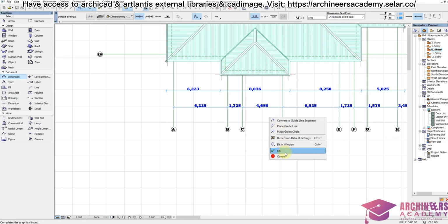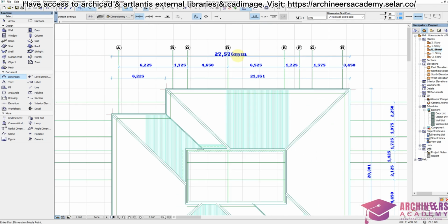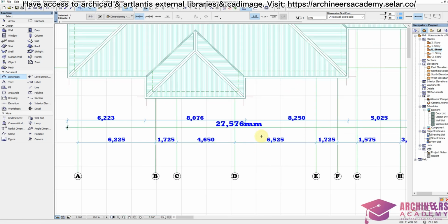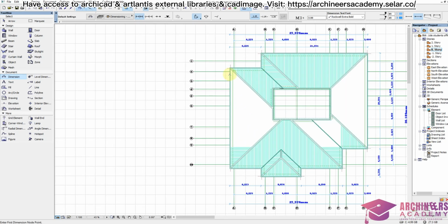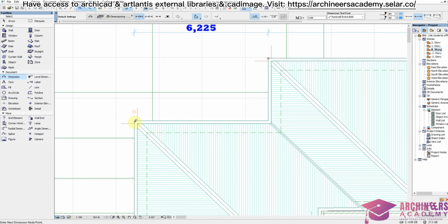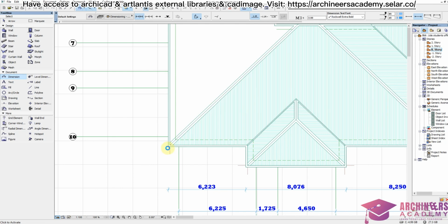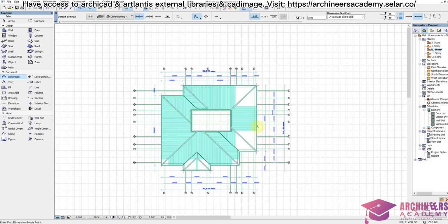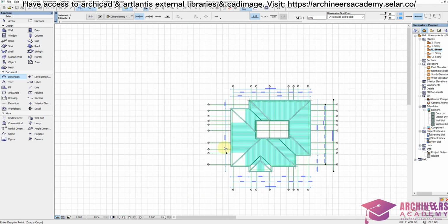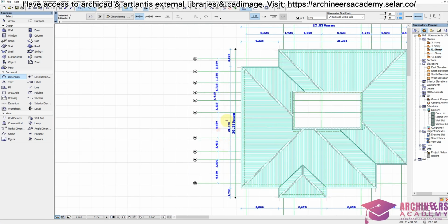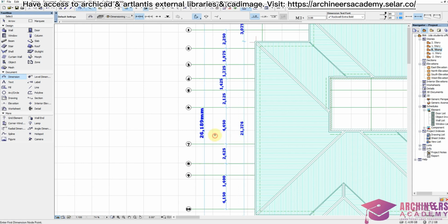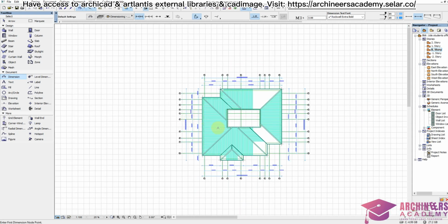Or you can choose to even copy, duplicate the one you have done here. Since they are exact, since the grid lines are the same, just copy. Control Shift D, just the same thing. So repeat the same process here again. So we repeat the same process. Just duplicate this. Control Shift D. So right now we are done with the roof plan.